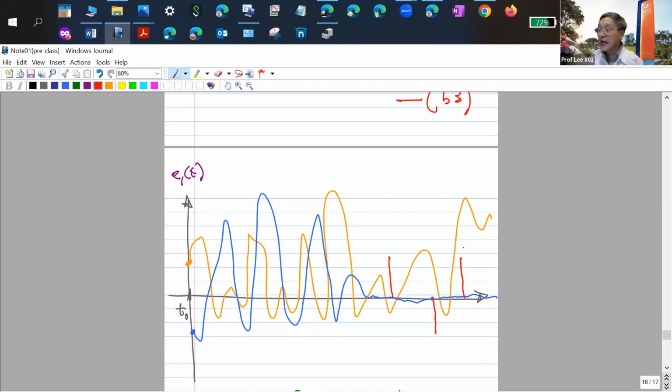This type of spiky signal in the time domain has measure zero. They do not accumulate integral. So that's why it's still dangerous, and we are not done yet, because if your adaptation is not done properly, most of the time your tracking error is zero, but suddenly it can spike, because L2 signals include this kind of signal.